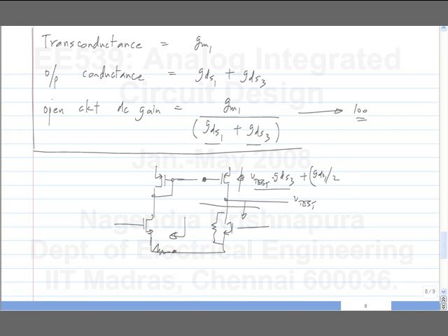And looking down here also you will get G1. So you will always get V test times GDS3 plus 2 times G1, where G1 is the conductance you look into here. But that does not have to be exactly equal to GDS1, because if I deliberately connect some resistance here, that will not be the case.